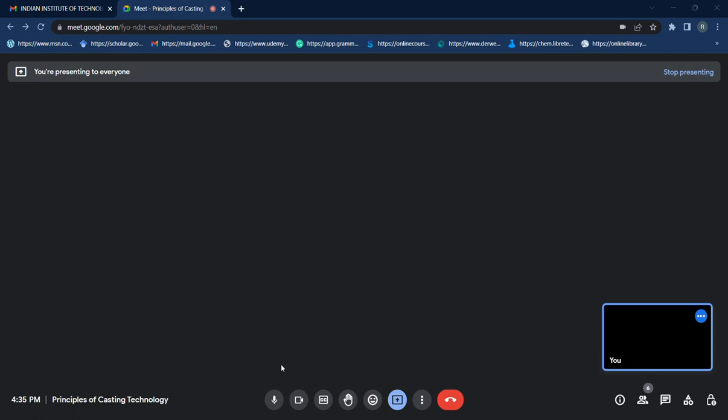From this you will find your volume of the riser as 0.5 of this. I'm directly writing here, so it will come as 551250 centimeter cube. So this will be your volume of the riser.